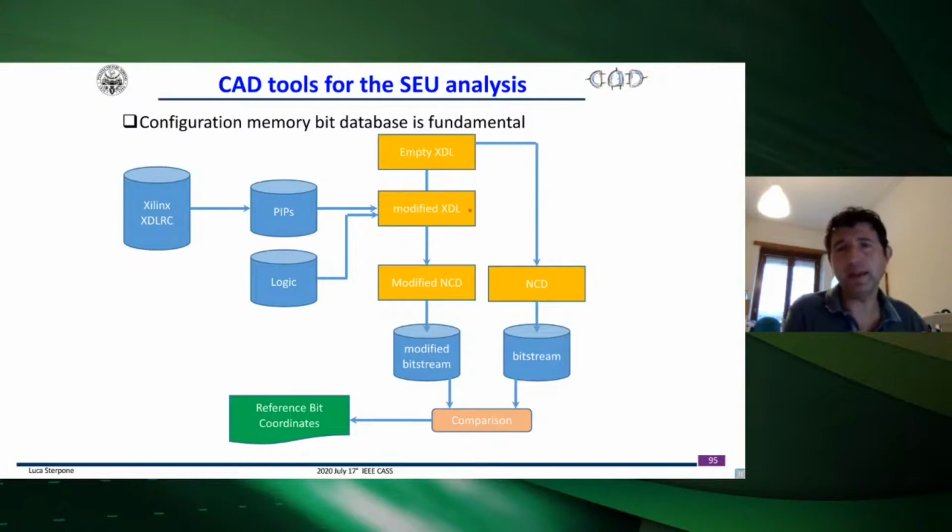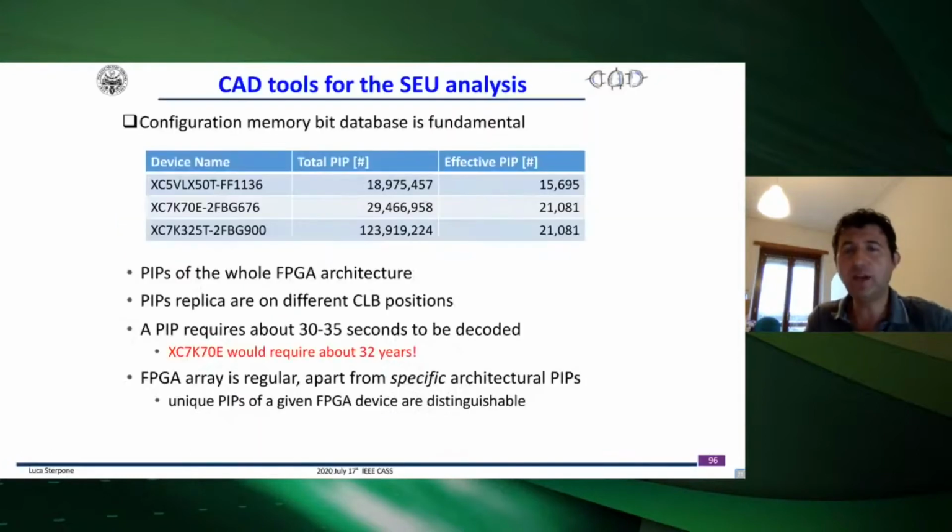So in order to perform this operation, you need to make a decryption of the bitstream of your FPGA, and you need to identify the bitstream reference, or the bit reference, adopted in the technology, that allow you to identify what are the resources that are used effectively in your application. If you're able to identify these bits, you're able to identify effectively what are the resources used.